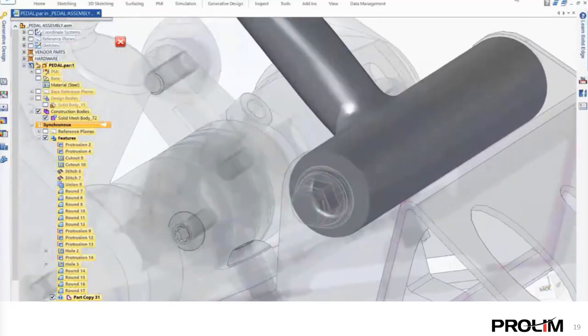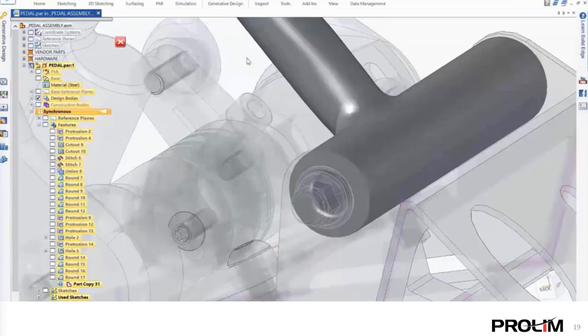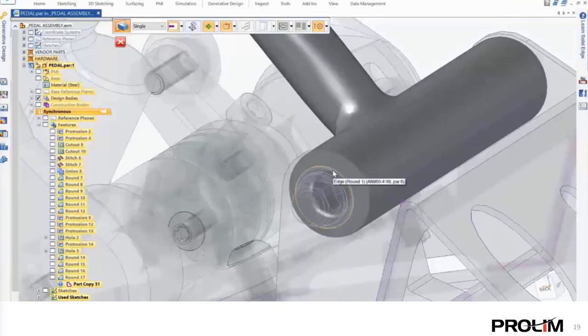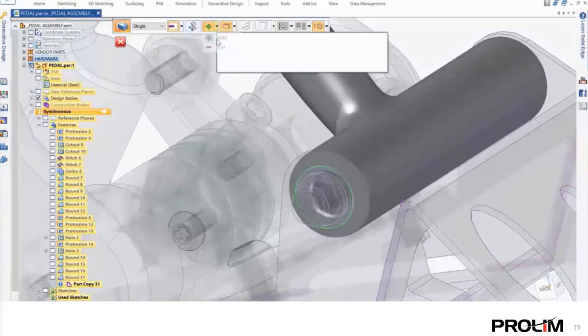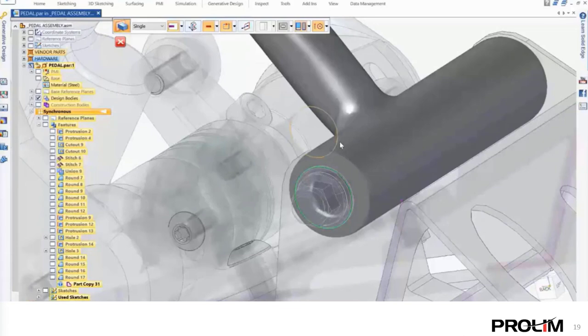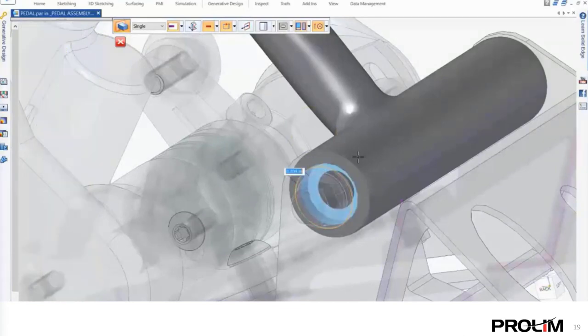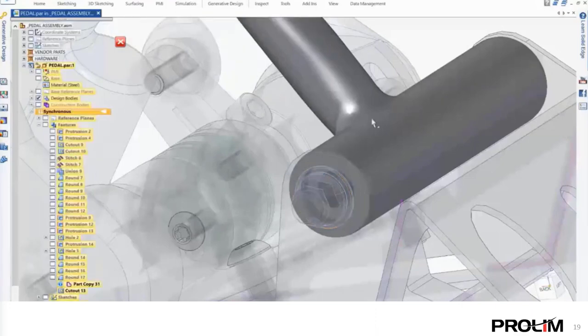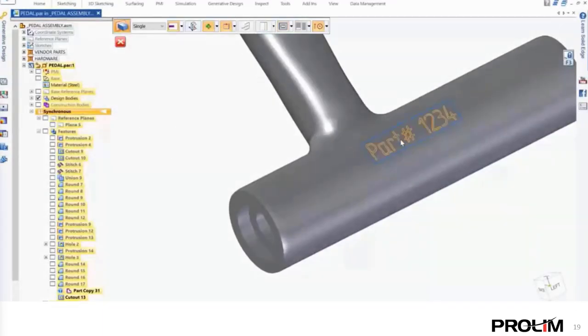A huge advantage in using Solid Edge to create and work with these generative designs, which are essentially mesh models, is when it comes to creating additional features of the design that we may need. With Solid Edge, adding and removing material is simple and fast. For example, a cutout can be added for the purposes of adding a bushing. The use of standard modeling tools makes this process quick and easy by picking up on some of the background parts in the assembly.